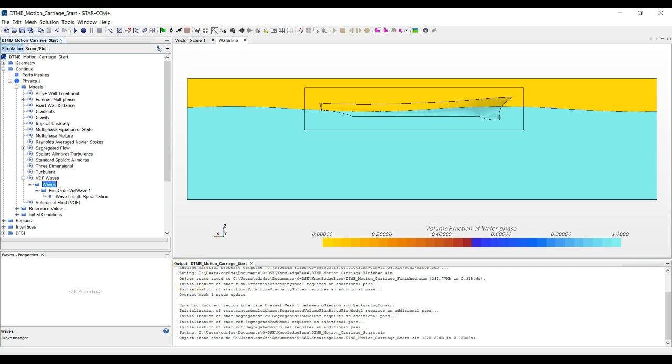The first is when simulating a vessel in a following sea, as the vessel velocity is superposed on top of the wave velocity for both the first and fifth order waves. This superposition model is not fully valid when the wave is propagating in the same direction as the ship, as for a static vessel the velocity components of the additional velocity and wave velocity would be opposing each other.